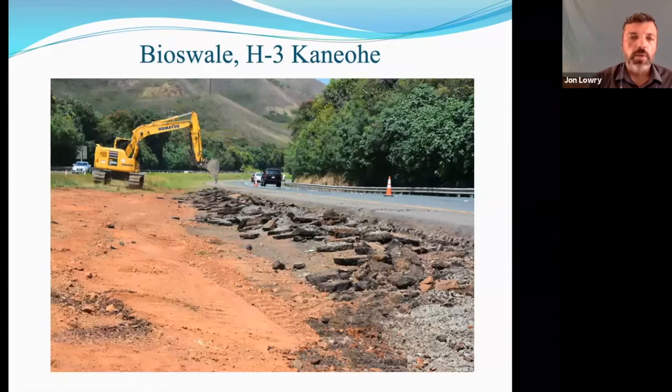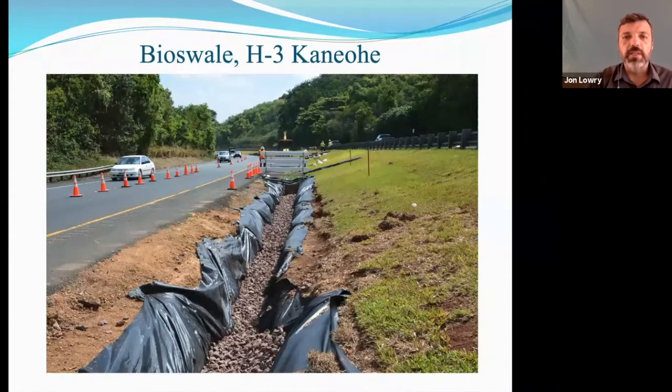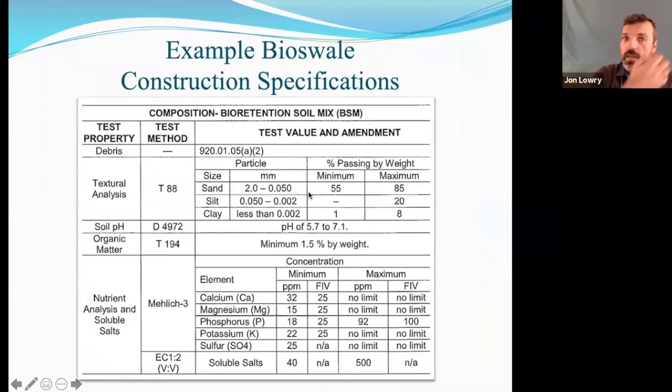So there were 26 locations where these concrete channels were removed. And you can see they're digging the bioswale. And in this particular case, they lined the bioswale. Only the sides of the bioswale were lined with a plastic sheeting. And then the bottom was left open for infiltration. And so here you can see them placing the aggregate storage layer. The next layer would be the